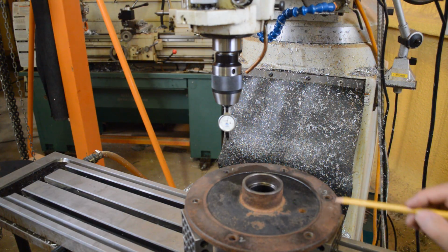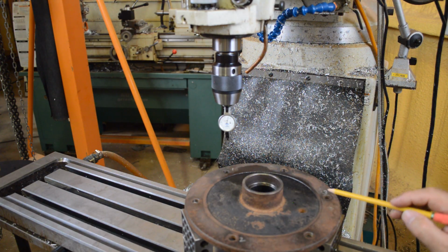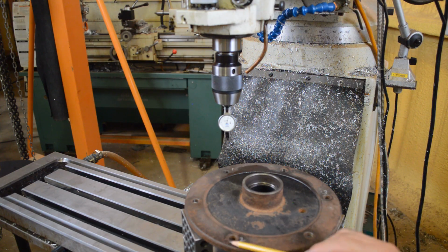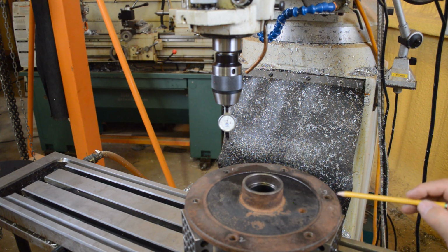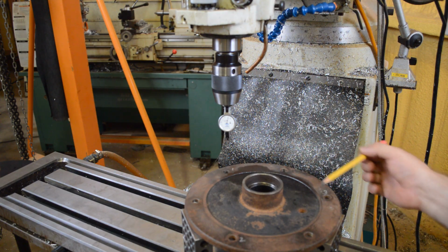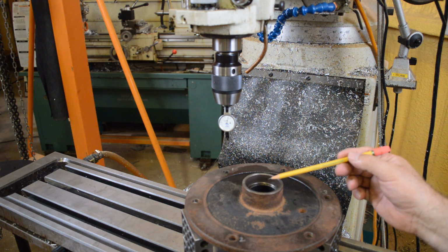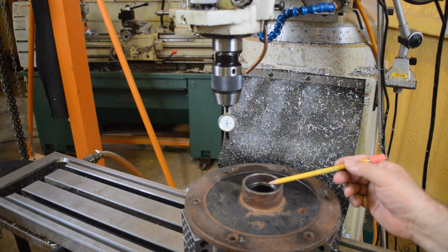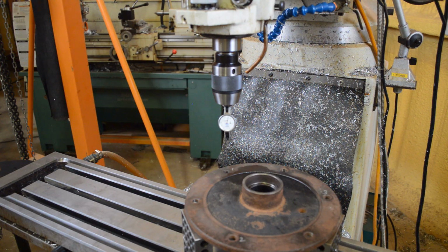All right, I'm going to pick up 3 holes on this flange. I'm going to pick up hole 1, 2, and 3. It's best to have these holes as far apart as possible, like this. These are 120 degrees apart. That's great. It's not a requirement, though. I mean, you could use this one, and this one. It's just that for the mathematical algorithm that computes the center of the circle to be as accurate as possible, you want the holes as spread out as far as possible, and that'll give you your best result.